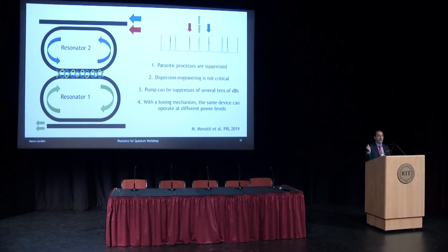since I don't need dispersion engineering, and if I have a tuning mechanism, I can push my resonances where I want, this device can work at many different pump power levels, because it can also work when self-phase and cross-phase modulation enter into the game. So for example, this means that I can work in the OPO regime at different power levels, because I can always decide at which pump power I'm going to pump without redesigning the device. I found it very interesting and very powerful.